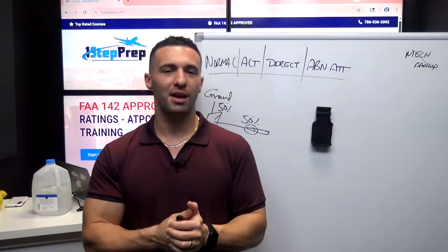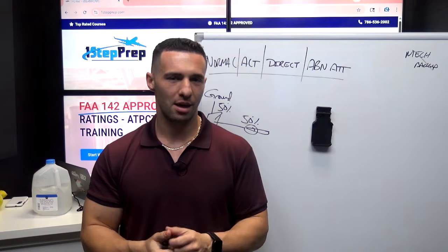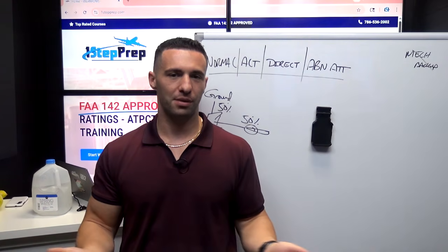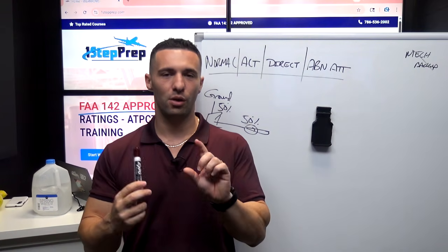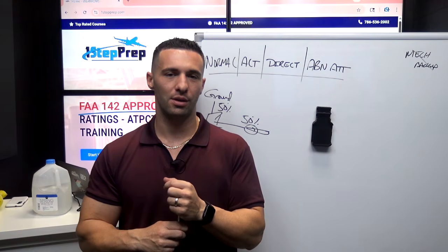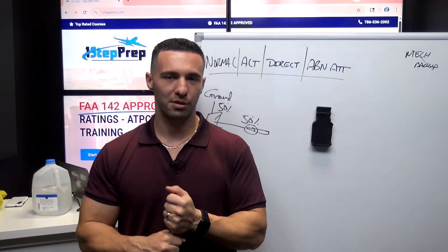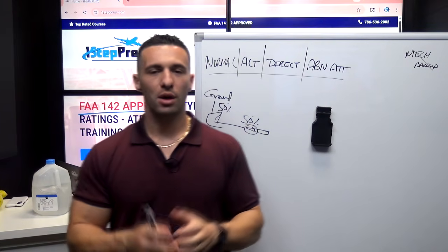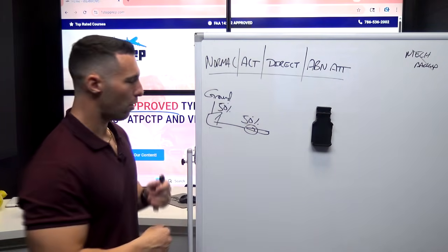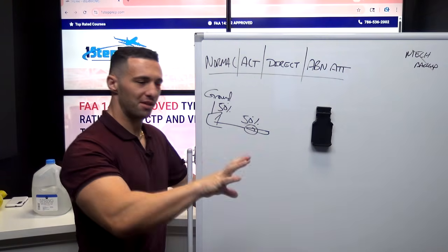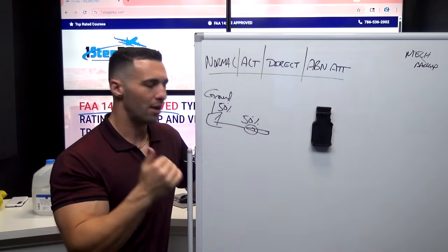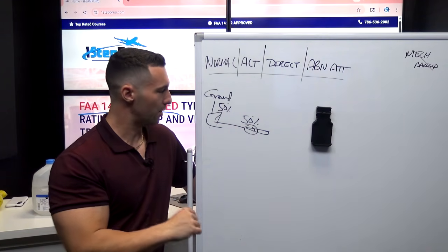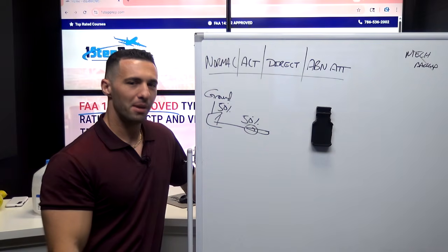But the crosshair is tied to side stick input, and it is not tied to flight control surface deflection. So even though you might see the crosshair moving on the attitude indicator, you may actually not have any surface movement at all from your elevator or aileron input. So when you do your full up, down, neutral calls, make sure you're looking at the actual system display page and not necessarily only the attitude indicator. So that's ground mode. Hopefully that makes sense.